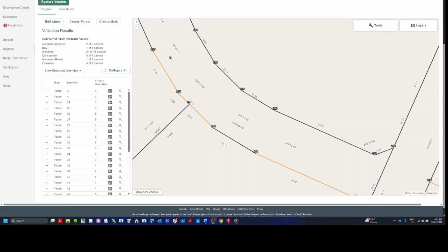And this is the same for easements where you might have easements with parallel lines. If you just provide the one bearing label in the middle of those parallel lines, we'll only be able to associate data with one line and not both. In the case where you don't have a road width label to add to it, the bearing labels will need to be provided for both sets of lines. So you'll need a bearing label for the top and a bearing label for the bottom line.